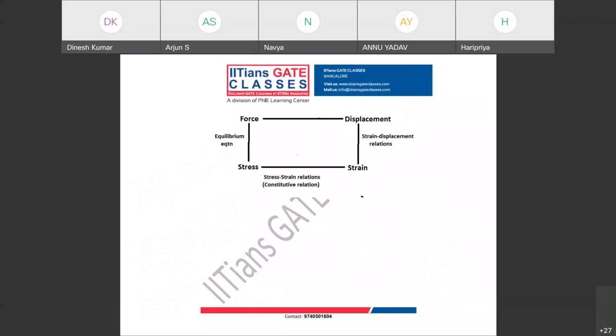So your margin of safety, MS, is always FOS minus 1, and your margin of safety should always be greater than 0 for any safe design, and your FOS should be greater than 1. Some industries use factor of safety, some use reserve factor. Both are one and the same. Reserve factor should also be greater than 1.